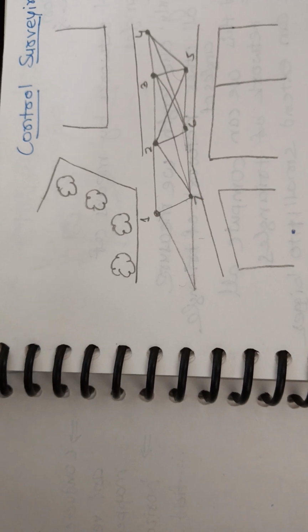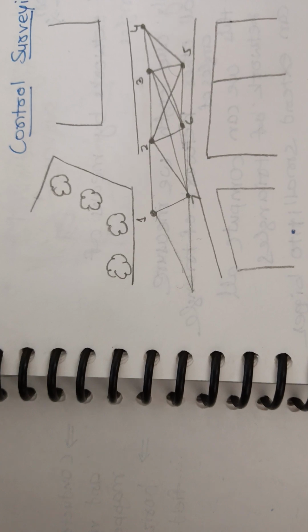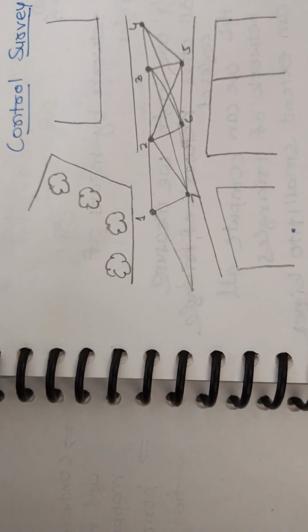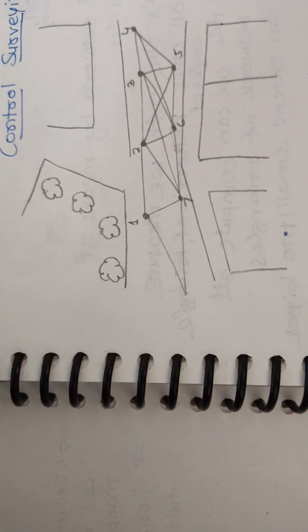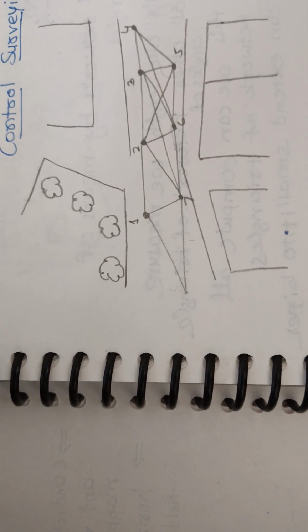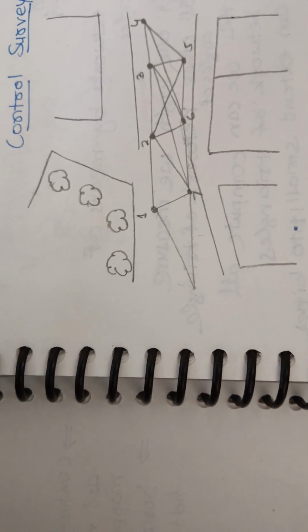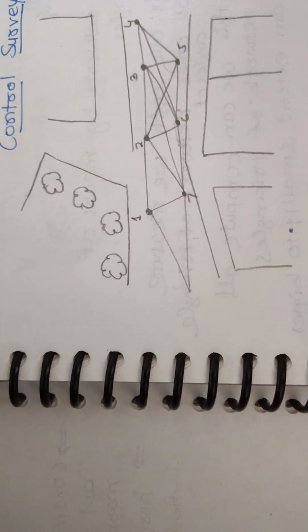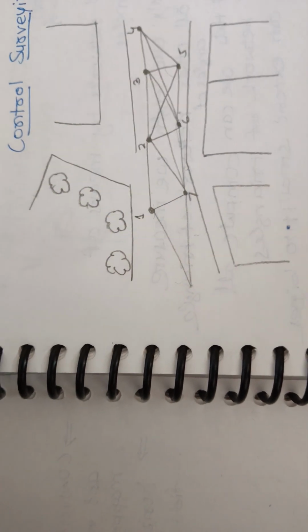Control surveying is the determination of the precise positions of a series of stations distributed over an area to serve as the origin or reference to be used for checking subsequent surveys to be used in engineering projects like property delineation, topographic and hydrographic mapping, and construction planning and design. Control networks which cover the whole country have been conducted with better accuracy and less stringent technique with the use of artificial satellites.